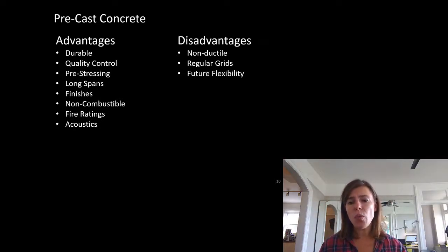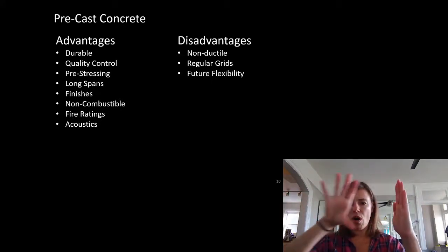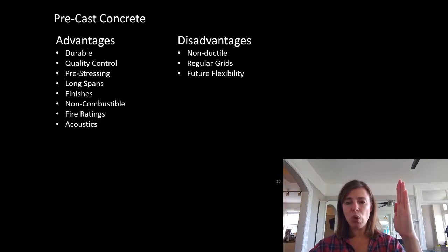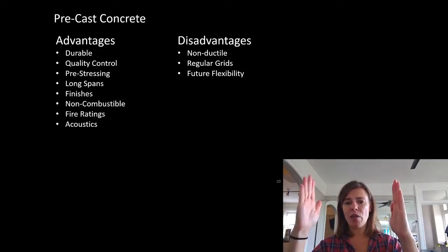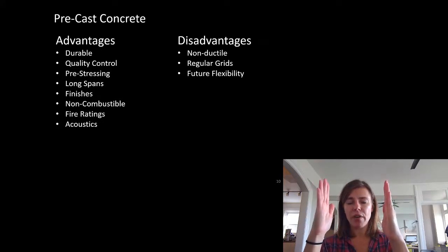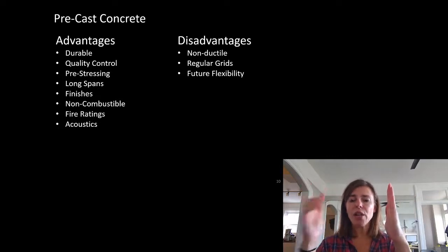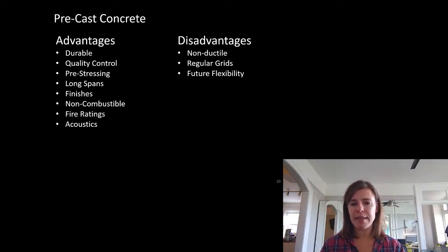So what we do when we pre-stress is we'll put a plate here, we'll put a tendon through it, we have concrete here, and then we pull really hard against another plate here. So we squash the concrete together so that if we tried to pull on that concrete, what we're actually doing is unloading that tendon before we switch to putting the concrete in tension. So we can build capacity into that system.